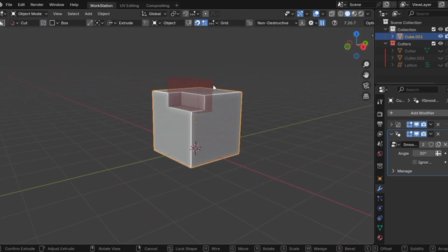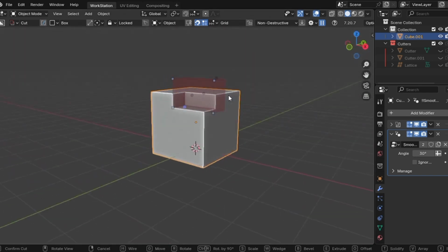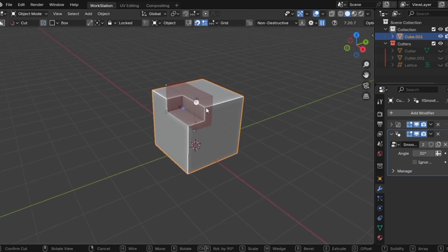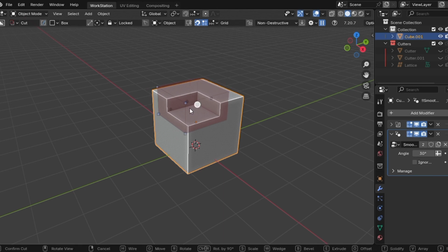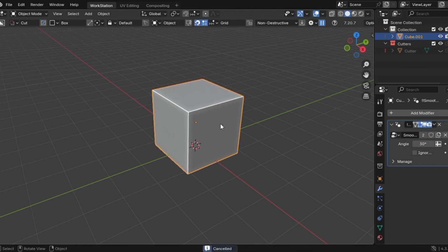Alternatively, if holding the button is uncomfortable, press the tab key during the operation to pause the cutter. It puts the cutter in a waiting state. To resume, press E or move your cursor near the cutter and drag the white dots to adjust. Listen carefully to this instruction to ensure you fully grasp the workflow.